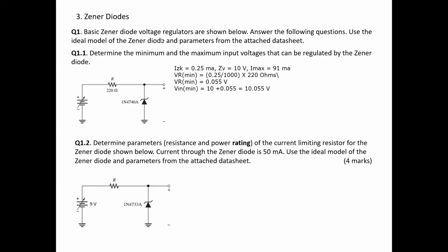Now this time, the maximum current that we can have is 91 milliampere. When we have 91 milliampere through this one, through the resistor we also have the same current. Now V R max, I will say the maximum voltage drop through this resistor, is 0.091. I just converted this current value into ampere. So that is 220, same as the earlier situation.